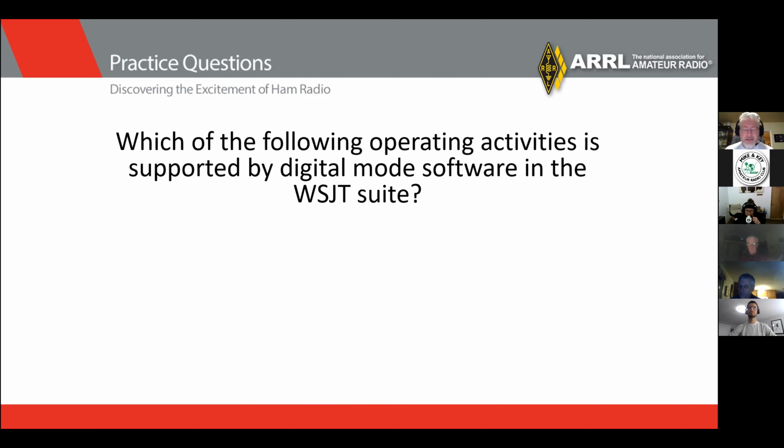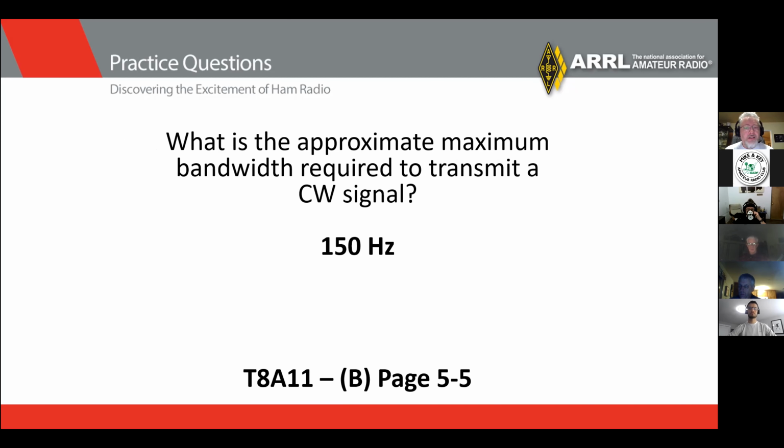Sorry, I have a question for the continuous wave one. Is it asking about Morse code? Morse code? So it is asking for the bandwidth, but really it is just transmitting a single signal, which is 150 hertz. So there is really not much bandwidth. You just need one frequency. Well, you're using a little small stream of 150 frequencies. That's what you're using. And it's a 4-to-1, so that's about 37.5 words per minute. I think what he's asking is, you're varying the carrier is what you're doing. Yeah, it's very narrow, right? It's the tone of the carrier.